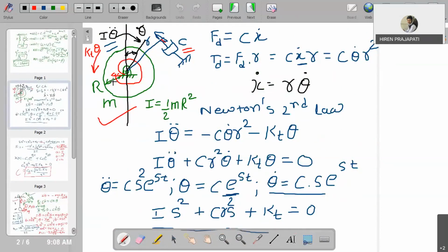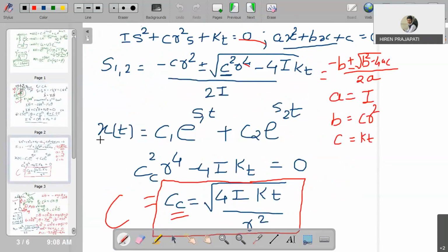Then for this type of system, what should be the critical damping coefficient? And what is the aim of critical damping coefficient? That critical damping coefficient gives the value of external damping which is required to give the system such that it would not oscillate, right? So that is the purpose of critical damping coefficient, right?